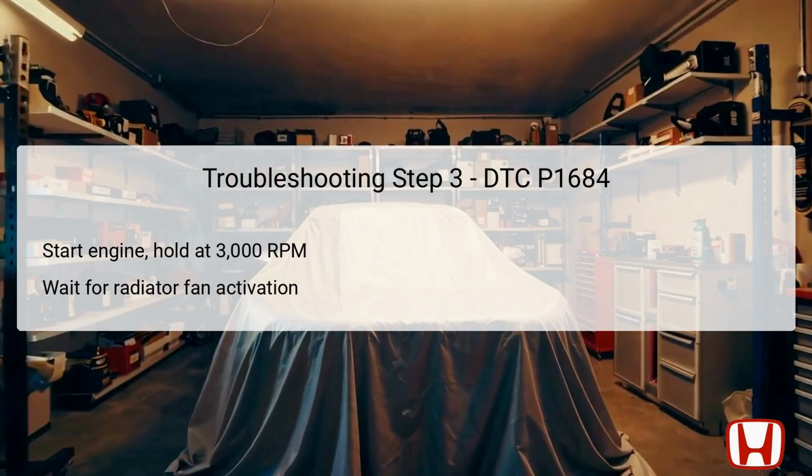The technician must monitor this stage until the radiator fan activates, which usually signifies that the engine has reached a predefined temperature. This action also serves as a stress test for the throttle body. Monitoring the throttle performance under these conditions helps identify whether the system is functioning correctly.